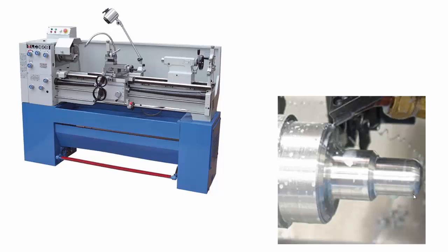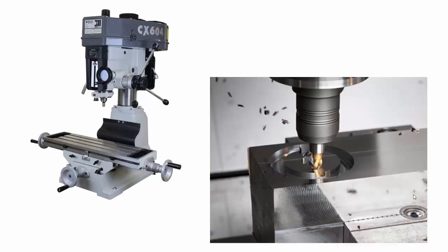So this is a very, very useful piece of equipment, again, for any solid that is a solid of revolution in nature. You can create stepped features in there. You can apply chamfers, you can apply grooves, you can bore holes into the part, and we call those operations boring when they're done this way as opposed to drilling. Slight difference in terminology there. You can also apply tapers. You can even create screw threads if you're cutting the screw thread. So these are common uses for a lathe. Here is a mill.